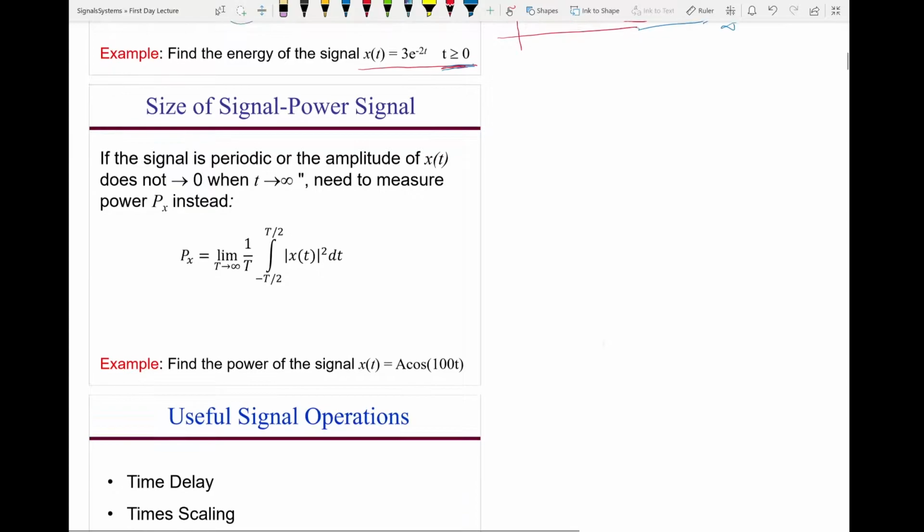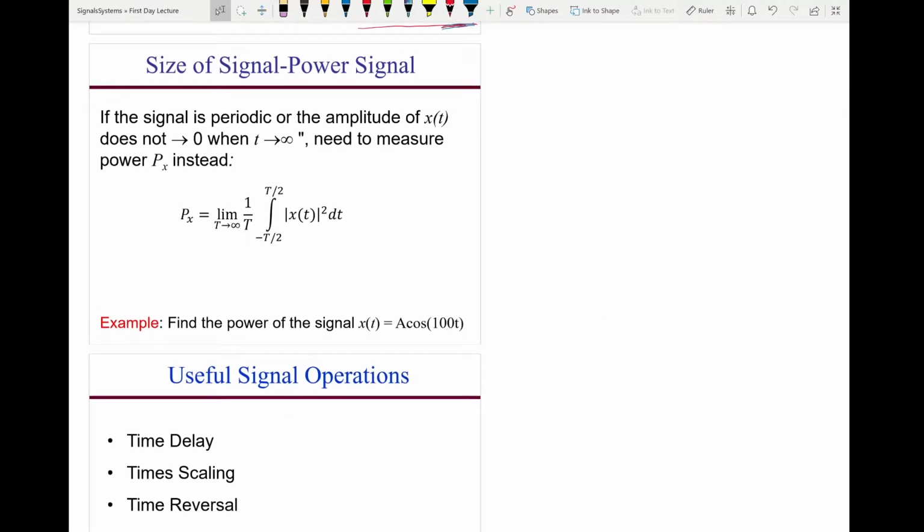Now let's look at the power signal. A power signal is simply sinusoidal. So when we talk about the power signal, that means it repeats itself. So the first step is, if you look at a signal like this, you have to decide how big T is. You want to choose T such that it is like a period of the signal, then the signal will repeat itself every T. If it's a clear sinusoidal, just take one period. If it's statistically similar to a sinusoidal signal, then capital T may be large, so you cover all possible aspects of the signal.